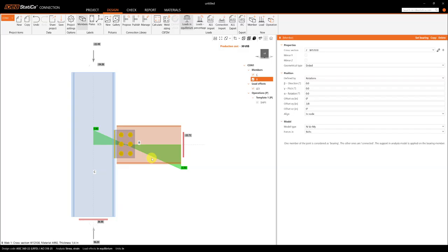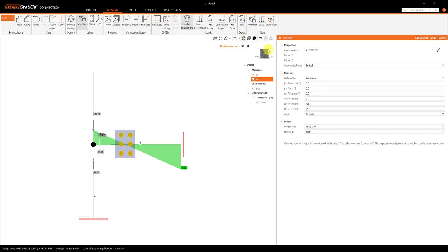It's recommended when you have a shear force to move it where you want that hinge location, that means where the moment is 0. In this case, we want to assess the shear force here at the center of these bolts. I'm going to delete this offset because we're always looking at one working point here.